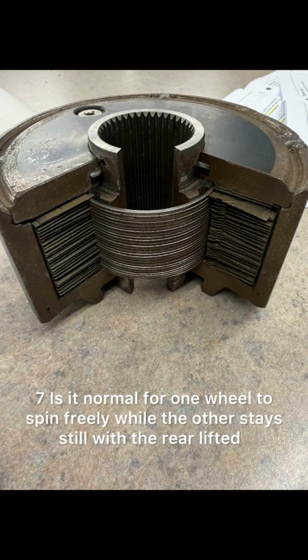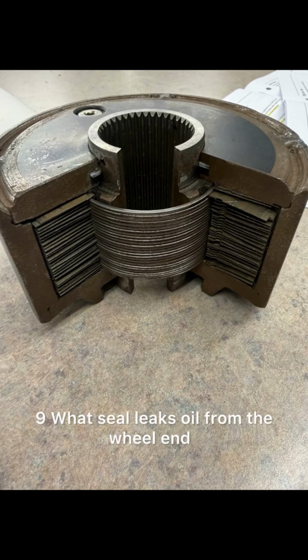7. Is it normal for one wheel to spin freely while the other stays still with the rear lifted? A. Yes, that is normal for an open differential. 8. What seal leaks oil from the rear of the differential? A pinion seal. 9. What seal leaks oil from the wheel end? A. Axle shaft seal.